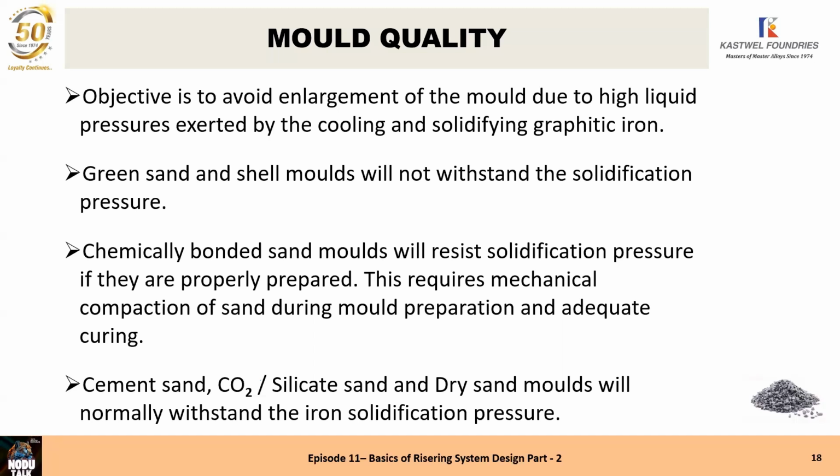Chemically bonded sand molds will resist the solidification pressure if they are properly prepared. By properly prepared, we mean mechanical compaction of the sand during mold preparation and adequate curing of the mold. Cement sand, CO2 or silicate sand, dry sand molds will normally withstand the pressure of the iron solidification. So the objective is to avoid mold enlargement.